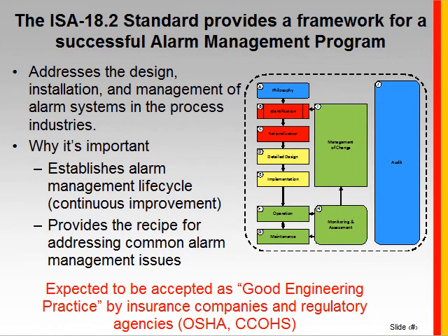So now along comes the new ISA standard on alarm management, released in 2009. One of the main goals was to address the performance issues that we just talked about, as well as to help prevent those accidents that we also talked about. This standard really provides a framework for an alarm management program. It addresses the design, engineering, operation, maintenance, everything you need to do to put in place and sustain a good, effective alarm management process.